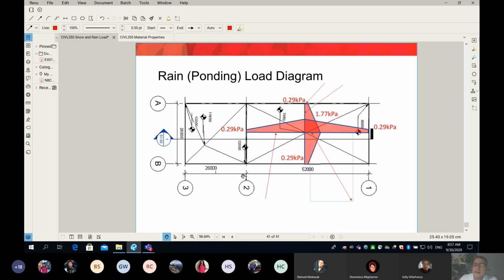Kind of agree, but it depends on the scupper's elevation. I know what you mean. I want to find the good answer for you, to be honest. If you imagine the slope of the roof and you put a scupper, how is the water ever going to exit through the scupper, because it's sloped so much that it's just going to go towards the middle through the building.